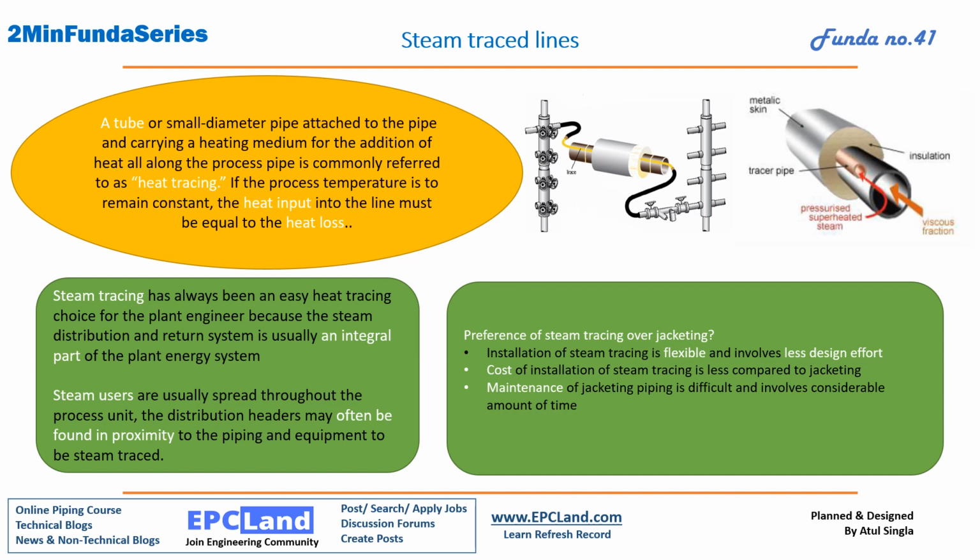Okay, now why is steam tracing very important? Because in any plant, steam is an integral part. So we can easily get steam distribution in any plant, a very commonly found thing. And the important thing is distribution headers may often be found in proximity of the pipe. Wherever we want to do the steam tracing, in most cases you will find the steam distribution header near the required one. So we can always distribute from that header.